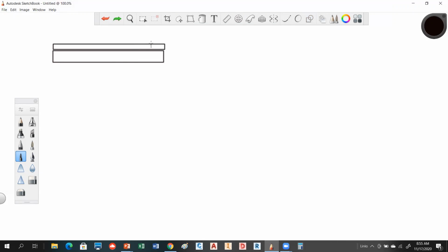So we've got a uniform load, so we've got loads coming across this beam, like you would have on a floor. So this could represent a floor joist. And that load rate is 3 kips per foot. Okay. And this span is 20 feet from side to side. And this happens to be a W12 by 50 steel beam.